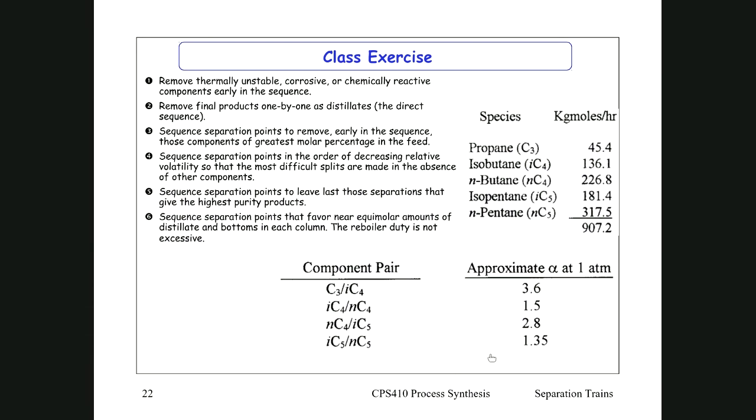Okay, there was somebody else who wanted to ask a question. Yes, Gabriela. I was also just going to ask if we should have changed the relative volatility to have the same reference component. But you kind of answered my question by explaining that you left it from the most to the top. Yes, it's more useful having the ones that are in sequence volatility wise, because that is ultimately where you're going to do a separation.